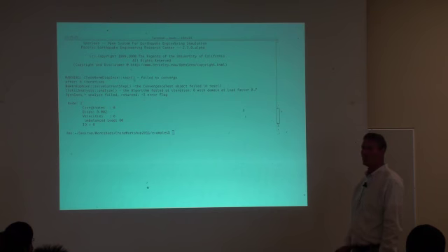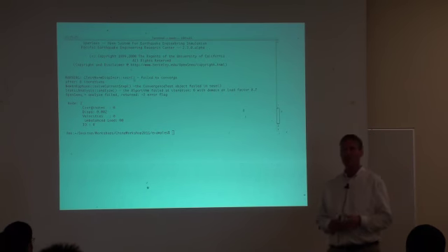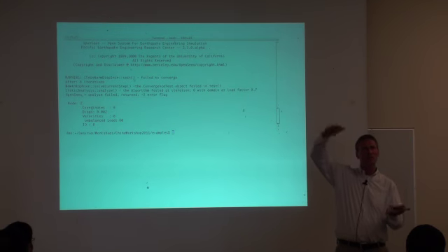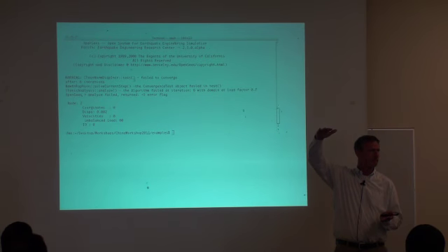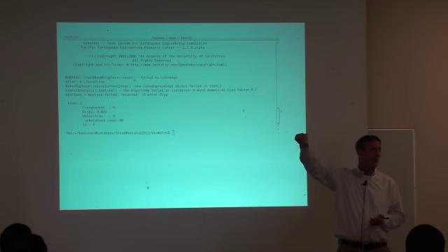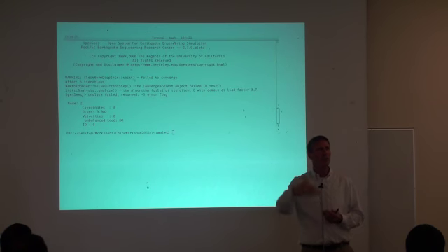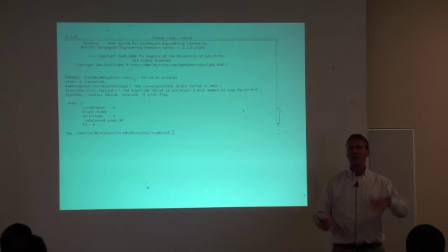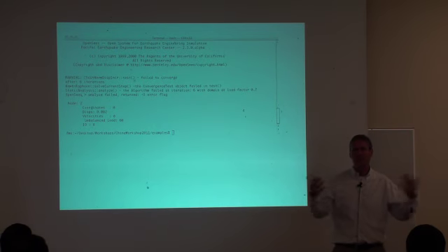Now here I am, I get up to 60. That is as far as I can go with load control. With load control, I keep increasing the load I'm applying, but at a certain point, all I can get is 60. I can't go any higher than that. But if I want to push the model further, if I want to see how much further the model goes, I've got to switch to something else. I've got to change my analysis.